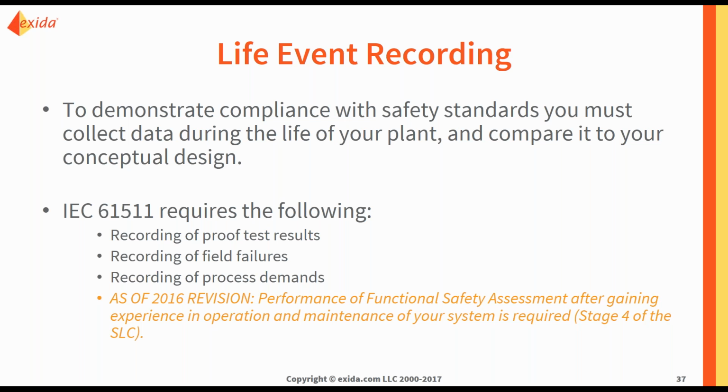As of the 2016 revision of IEC 61511, performance of functional safety assessment after gaining experience in operating and maintaining your system is required. So that's stage 4 of the safety life cycle. I believe it was always suggested, but at this point it is a requirement. So you want to make sure you record your proof tests, your field failures, and your process demands.